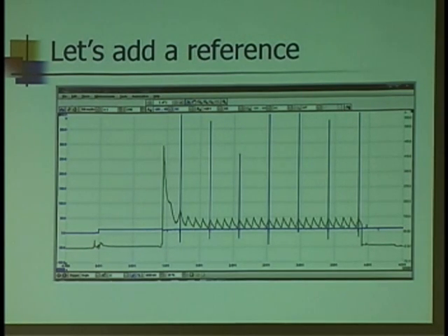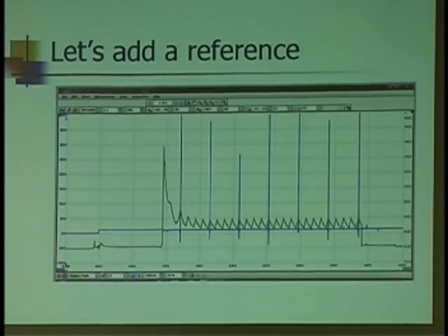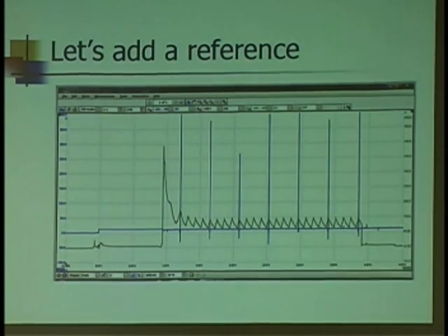What I really like this for is when you're dealing with any kind of transverse design. You might be able to get to the front bank fairly easily to do a traditional compression test, but it's a bear to get to the back. I've looked at the flat rate on some of those. It might be 2.5 hours. Where I live, that means I would be charging my customer $250 to $300 for a test that may or may not show anything. They're going to like that. But if I can say, here, Mr. Customer, I have this capture I want to show you, and explain what it means. It's showing that there's a weakness in XY cylinder. Now I have justification to spend your $300.